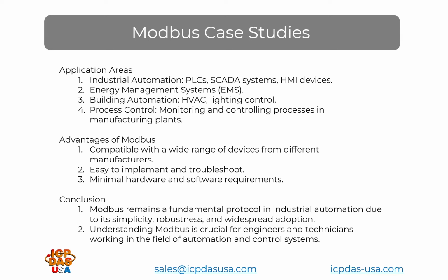And we have that Modbus master tool, which you can use to send a request for data for one register, and then send a request for another register and see what value that register has. Ideally, you want to pull a value with a known register. I, for instance, like to find the product name for our modules because it's always like the part number itself, or there's certain ones that maybe have the baud rate setting, or some other function, so you can verify it's the right value.